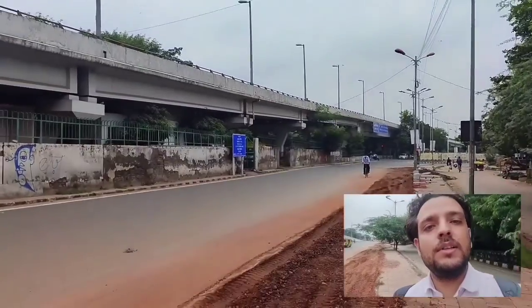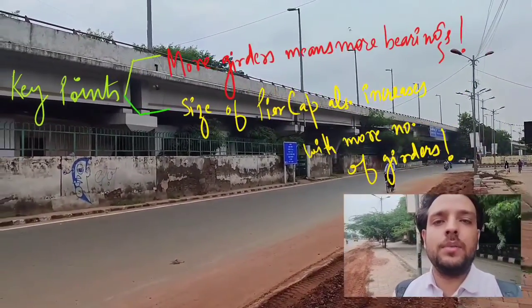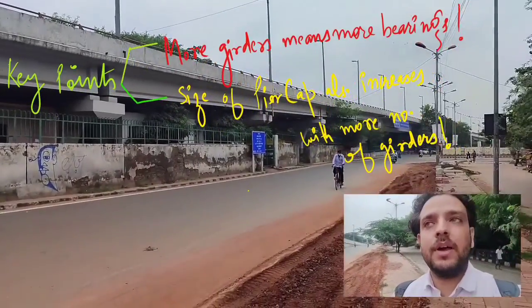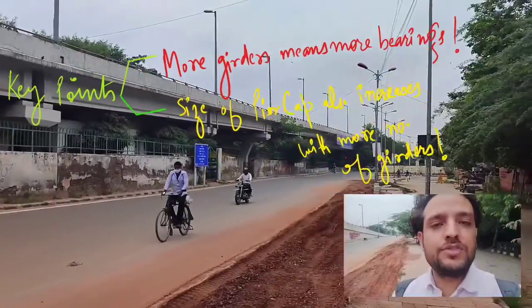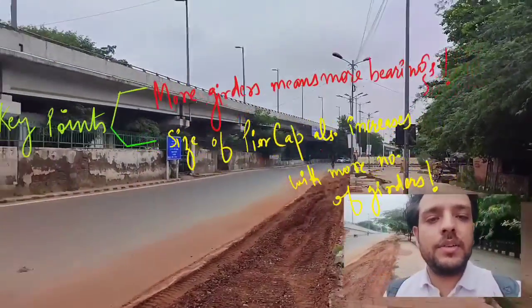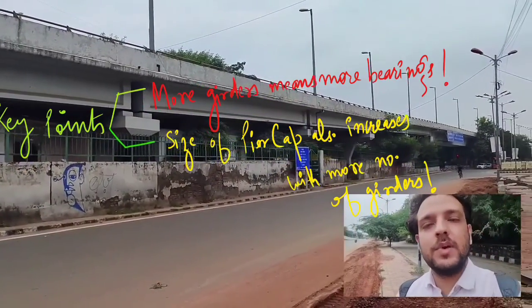Not only this, the number of girders also increases the number of bearings required over the pedestals, over the pier cap, and in such cases even the pier cap width may be increased. So there has to be a very detailed calculation about the number of girders you adopt and the spacing between them.